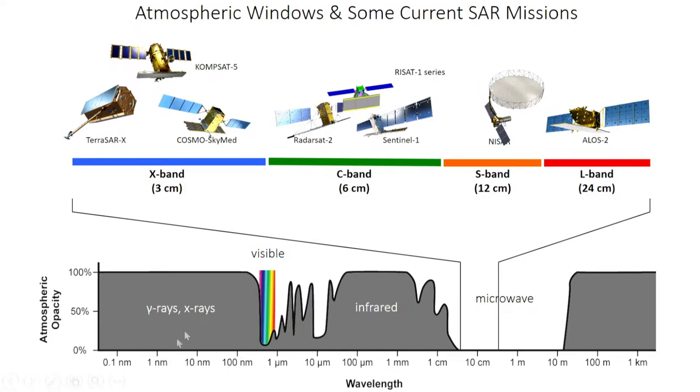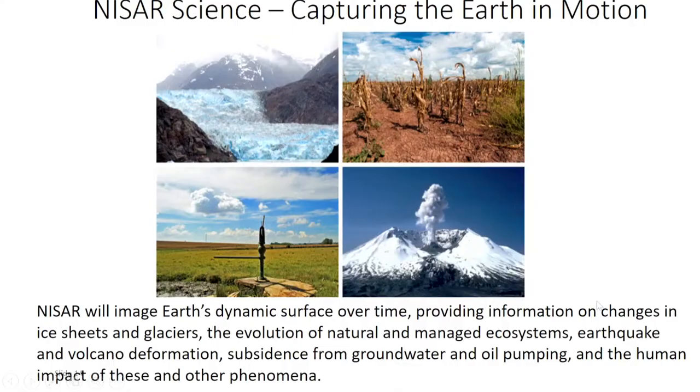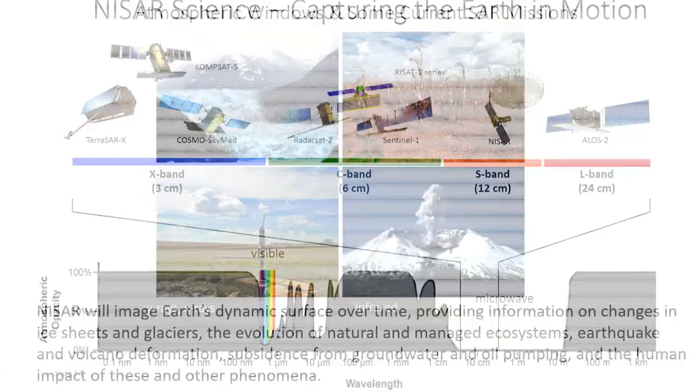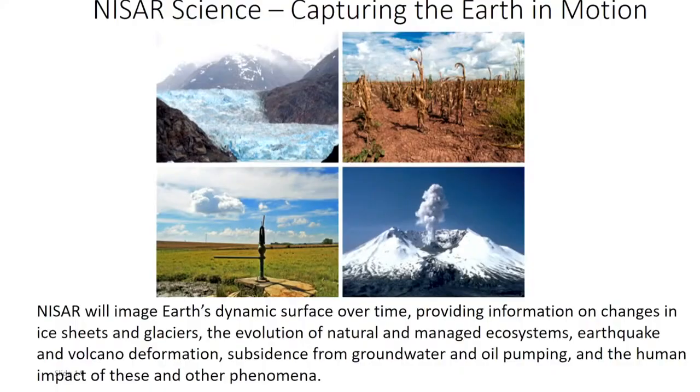Very few satellites, none really, work in the X-ray range. Few work in ultraviolet, but most satellites work from ultraviolet to microwave range. Radio waves you will find mainly with ground instrumentation, because satellites in that range are not possible due to the limitation of antenna size.